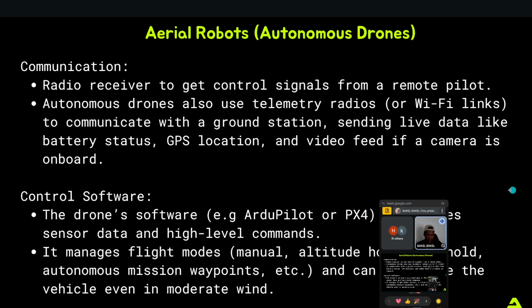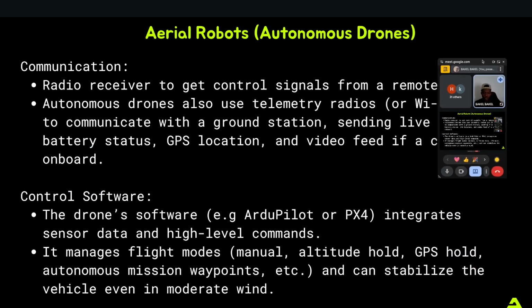For the control software, on the robot dog, I didn't go into the control software because that's a bit closed, a bit, how do I put it? It's proprietary, right? So on these drones, we have a lot of open software. We have ArduPilot, we have PX4. Then that's your normal Pixhawk or something. So basically, they help with that low-level thing where you want to move forward and then it speaks to the motors. It's literally a firmware kind of thing. And then you just focus on writing higher-level code.